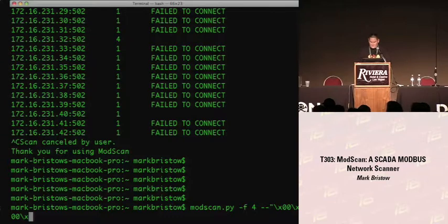So 0, 0, 0, 0. Oh, yeah, did I do my X yet? Okay. 0, 0, 0, 1. Okay. Well, what does that mean? For reading registers, the first two bytes say what address we want to start at, in this case address 0. And then the next number is how many addresses you want to read: 1. Nothing too special about that.